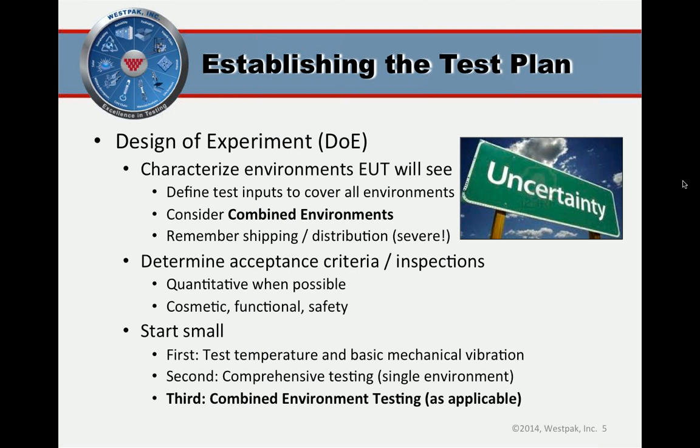When you're doing all this, think about doing a test to level or test to failure. So what we mean by this is test to level would be the minimum requirement your product needs to survive through to be something you're willing to put your name on and sell, whereas test to failure would be continuing testing beyond that, either at a higher level of intensity or for longer duration, to see how the product will ultimately fail, and then hopefully learn from that and make improvements to your product from those learnings.